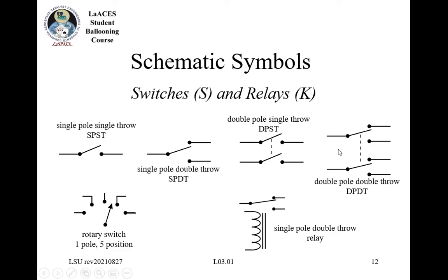So why would you use, say, this double pole, double throw? So there's a few reasons. Sometimes you can get more current out of these, relays will be rated for some current. That's something that you should be very aware of so you don't damage the device. And so sometimes people use this to double up in order to get more current across the contacts. I like to use these when I design things, I use one of these as a status bit and then the bottom one to actually switch power.